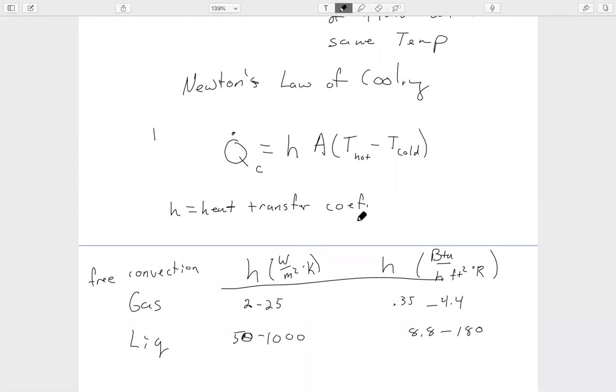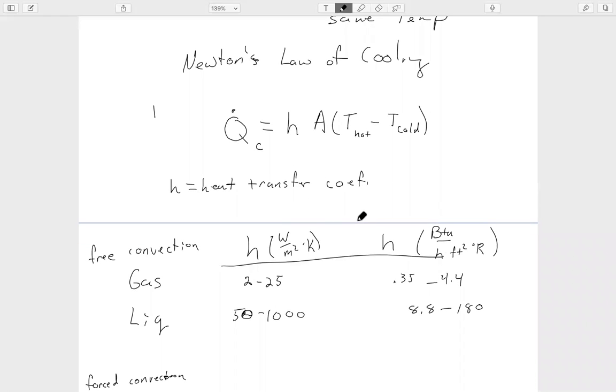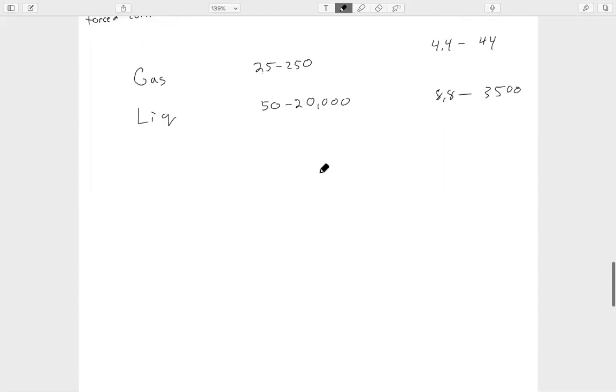As far as the minus signs go, the heat is going to flow from hot to cold. So when you're talking about a heat transfer rate, you need to think about the direction of flow. Use the fact that heat flows from hot to cold to figure out the minus signs. That's much easier than memorizing all the special cases. Just think it through in each problem. If you get it wrong, you'll get a fireplace cooling off the room instead of heating it up, so it should be obvious if you get it backwards.